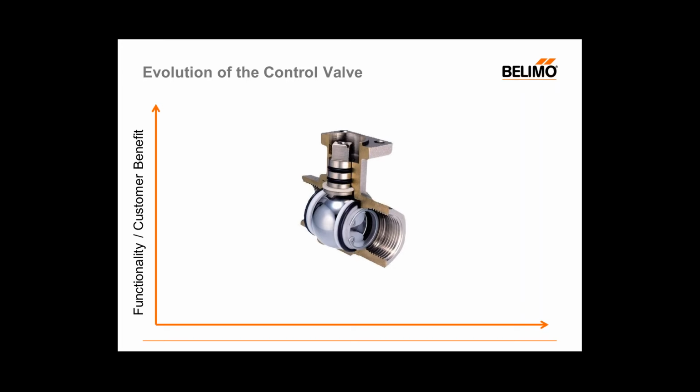And the reason we call it position control is that the control signal sends a signal to the valve that dictates how open or closed the valve is. It really defines the size of the opening that the water has to flow through. So we're controlling the position of the valve. We're not controlling how much water goes through it. We're not controlling how much heat transfer we have.